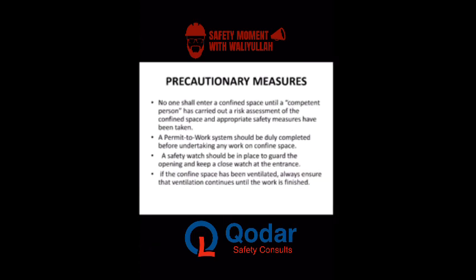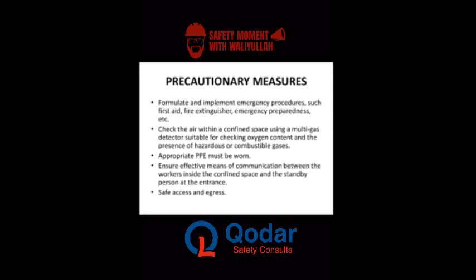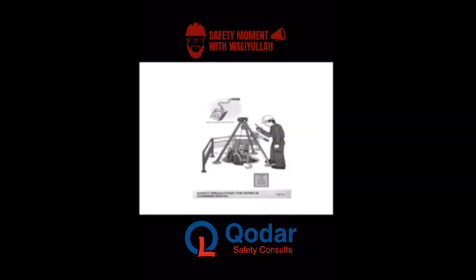Please, when working in a confined space, no one should enter until a risk assessment has been done by a competent person and appropriate safety measures have been taken into effect. A permit to work, of course, is always there when working in a confined space. A gas test also has to be done. First aid materials, extinguishers, emergency preparedness should also be on ground.